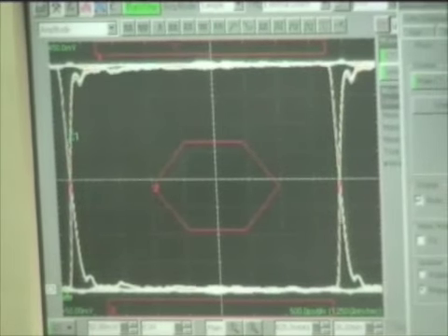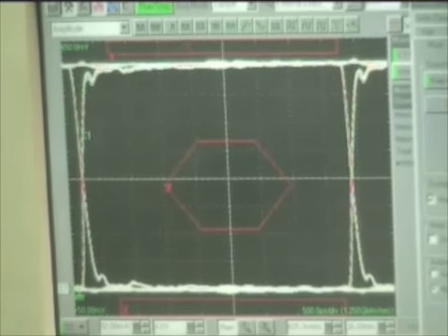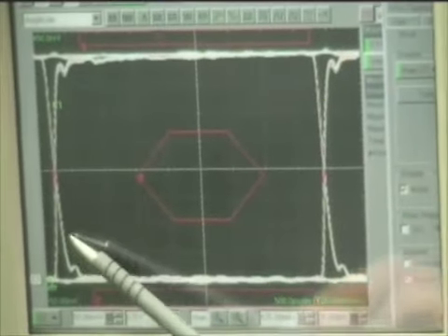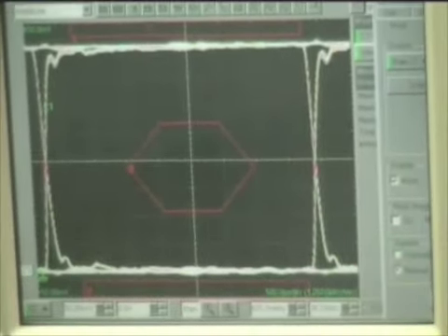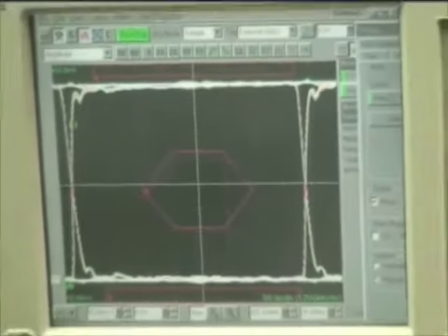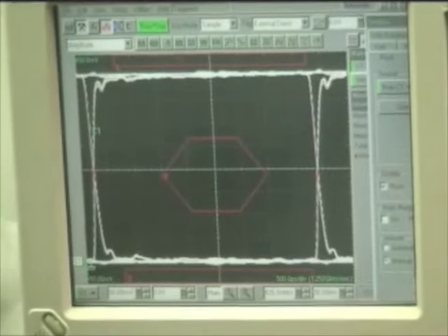The I diagram demonstrates the ESD9L has logic levels with no distortion to the rise and fall times, as we saw earlier with some of the other parts. This option leaves the designer with budget for other components that add capacitance to the line and also helps maintain the signal integrity of the USB line.